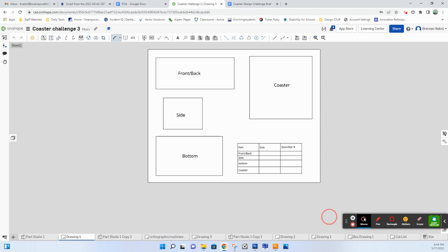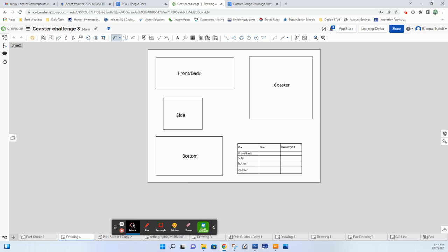There's another tool in here if you don't feel like going back and forth to your model or to your other drawings. Down here, there's a little tape measure called the measure tool. If I click this, I can just click the line and it will tell me over here the length of that line. And I can also go from point to point. So while I'm still in the measure tool, I can just click on the specific point.